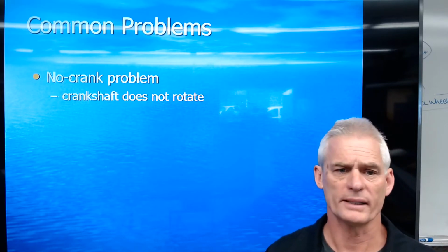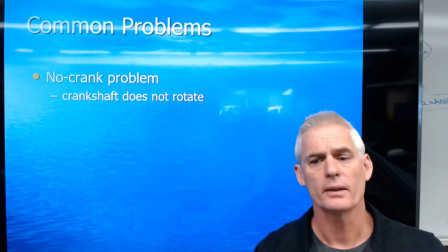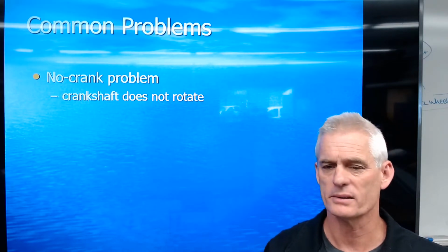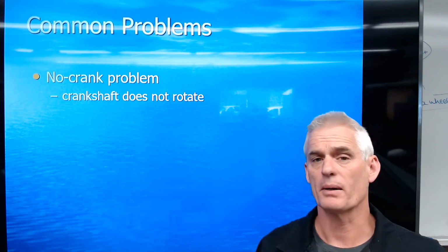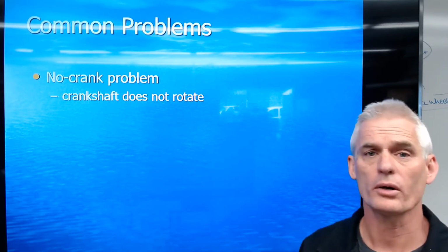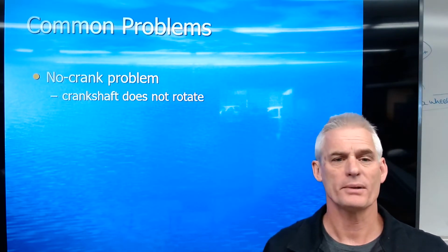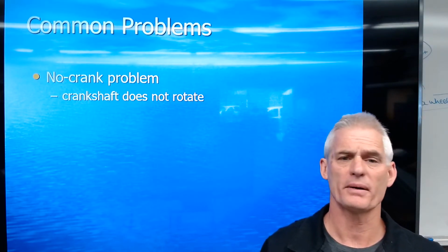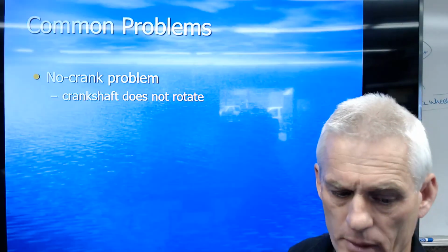So in most cases, the first thing we're going to do is look at the battery, and we have a way of testing the battery and really quickly deciding if it's a battery issue or a starter issue. And then we've got to think about things like maybe an alarm has been tripped, maybe it's a key issue, maybe I'm not in park or neutral, maybe my foot's not all the way depressed on the clutch, etc.